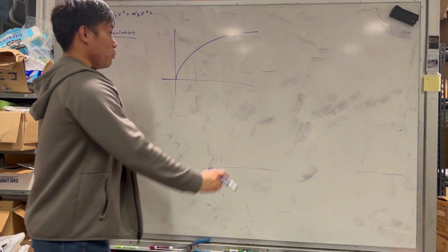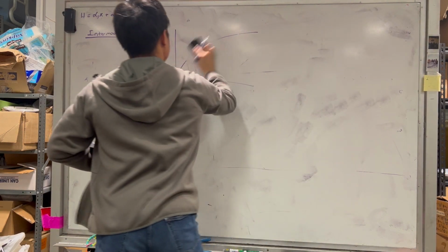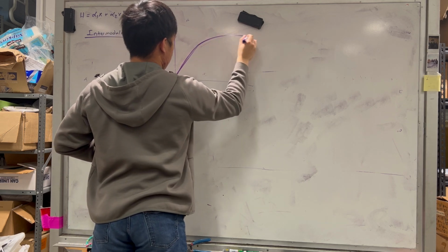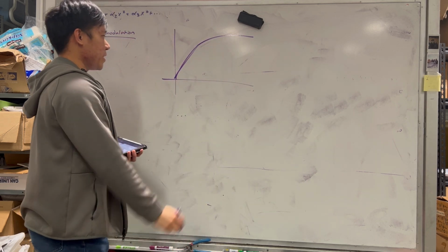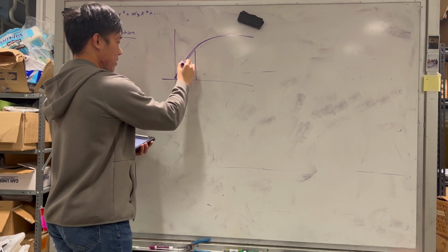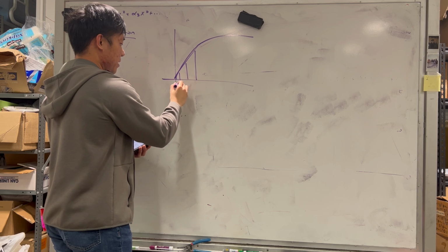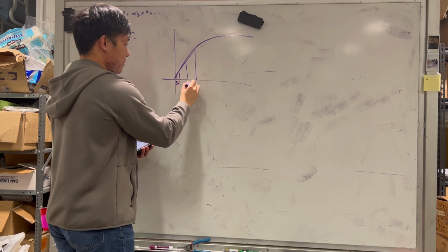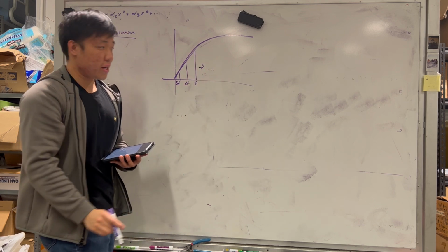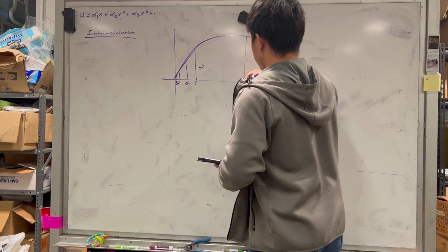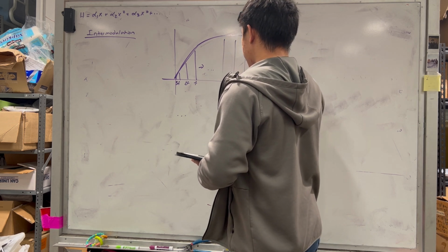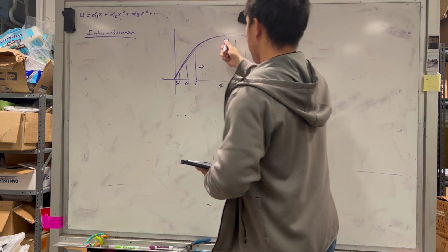Why do we see them more than we did? Oh, it's because all of them aren't that strong, their amplitude is lower. So think about it like this. In the beginning, your fundamental has this strength, and then your second and third, let's say this is your 3F, 2F, F. As you walk along and increase the strength, suddenly all three of your frequencies here are all gain suppressed.